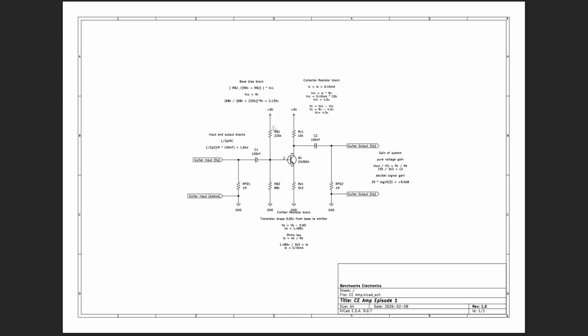And then we have this division here that happens, which essentially means that our guitar input signal gets added to the 2.1 volts that results at this pin 2. And then we lose some of that 2.1 volts coming in here, and we end up with 1.5, let's say, volts at this point.